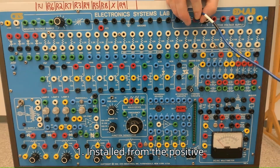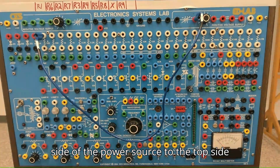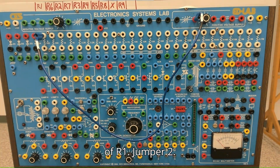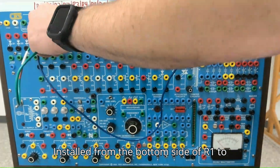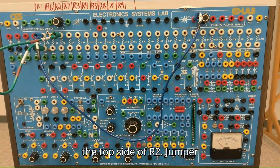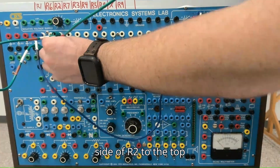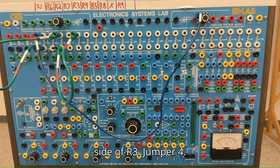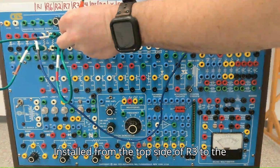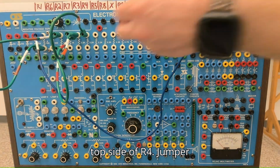Jumper 1. Installed from the positive side of the power source to the top side of R1. Jumper 2. Installed from the bottom side of R1 to the top side of R2. Jumper 3. Installed from the bottom side of R2 to the top side of R3. Jumper 4. Installed from the top side of R3 to the top side of R4.